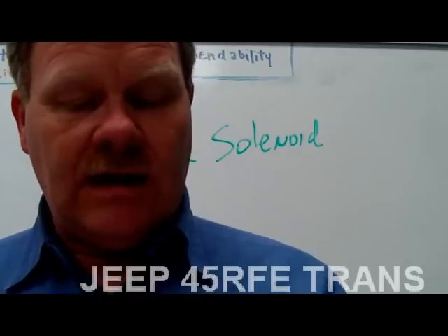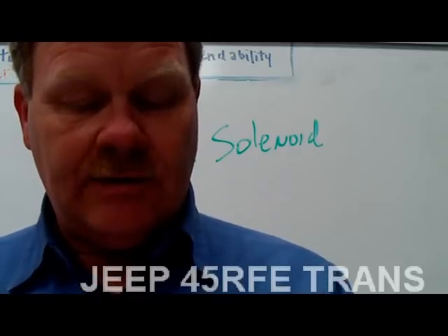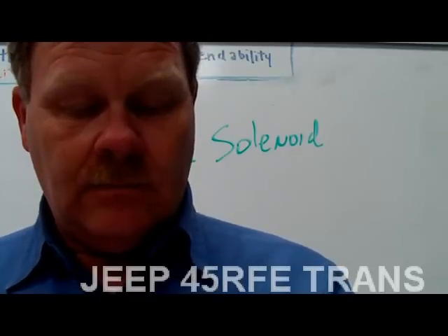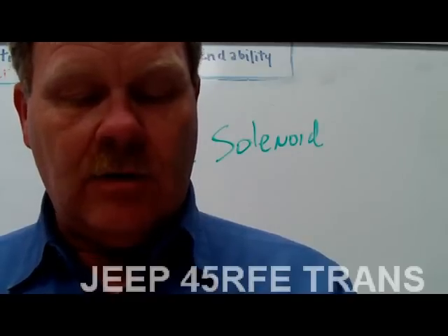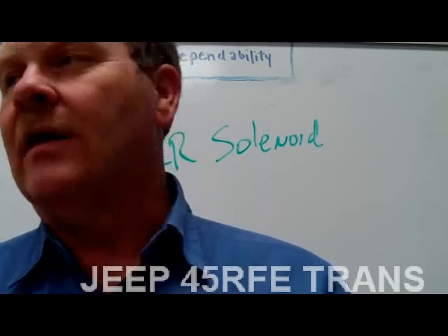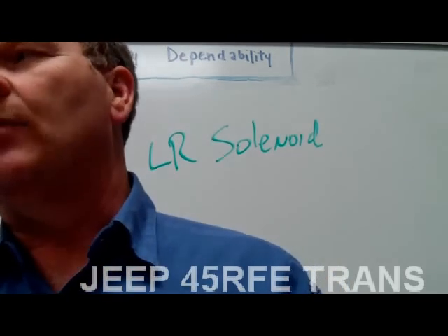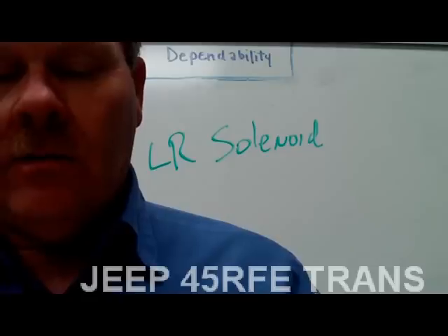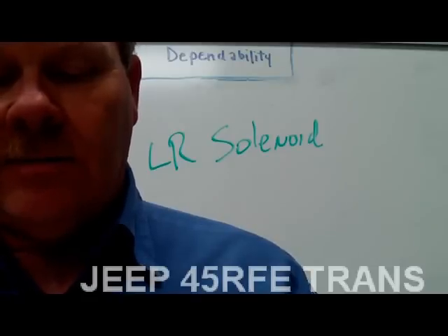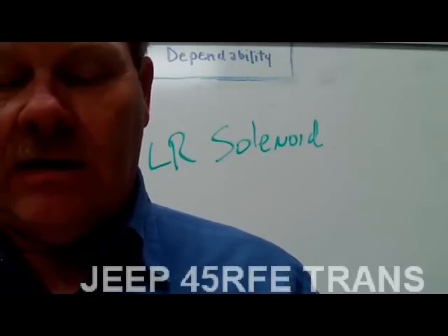Which of the following is not a direct TCM input? Anybody know? Come on, think about it, guys. Pressure control solenoid is not an input. It's an output, right? Got it? When attempting to narrow down a problem with a transmission operation, you should start by doing what?